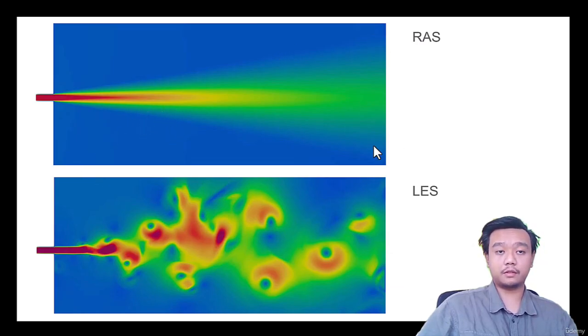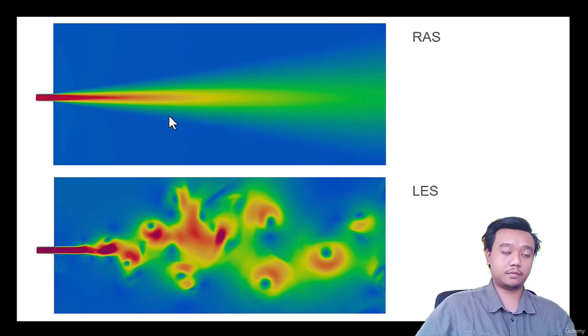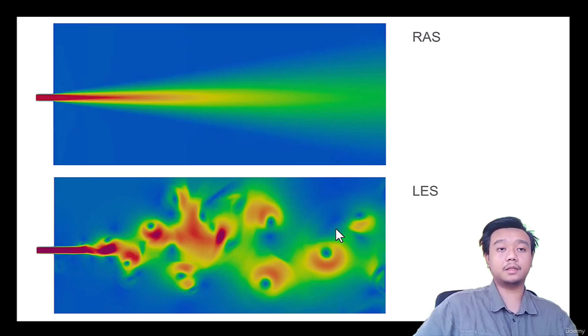to solve that. And again, computational fluid dynamics is all about the modeling technique. So it highly depends on your application. If you want to compare two models of a racing car, let's say, or maybe you have ten models, you cannot solve it by LES. Of course you can, but it will not be computationally feasible in terms of the time and the computer effort.